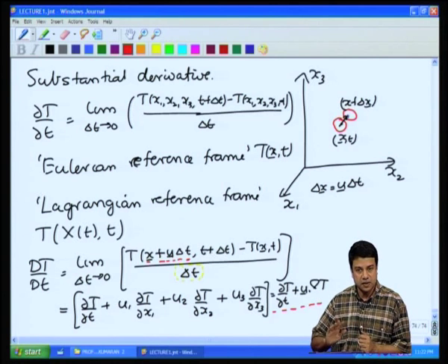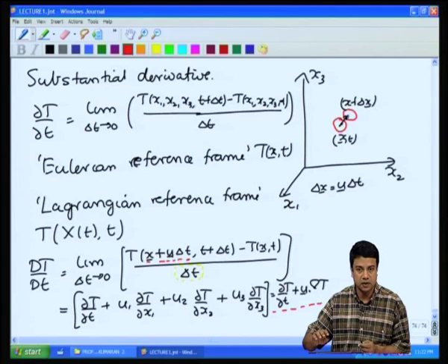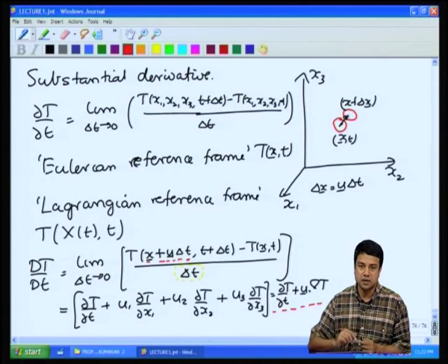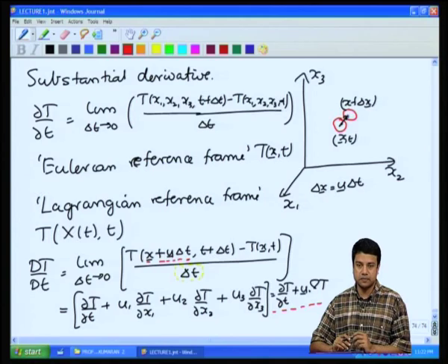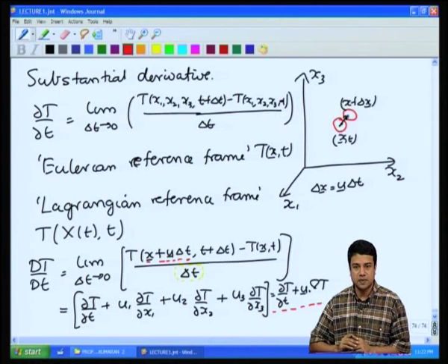That is because as the fluid moves, this volume element that was at location x goes to x plus delta x. Some other fluid occupies the location x, and there may be spatial variations between nearby volume elements of fluid. If the temperature is not diffusing, then the temperature on a moving element of fluid is constant. It may be spatially varying. So, in that case, it is the substantial derivative that will be 0. The partial derivative in general will not be 0. Okay. So, that is the substantial derivative.